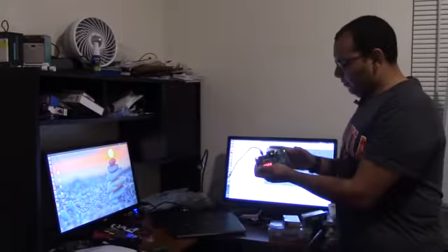I saved it here in example 1. I already generated the bit file, so we don't need to generate it, and I say open target and device, and you run. If you see here, I connected the computer to the board through JTAG from this side and USB from the other side.